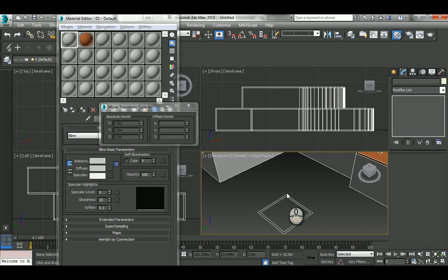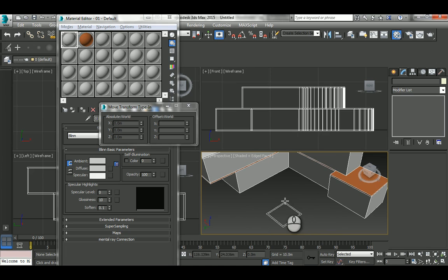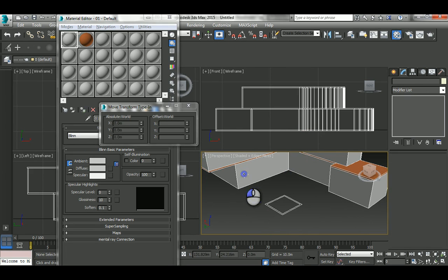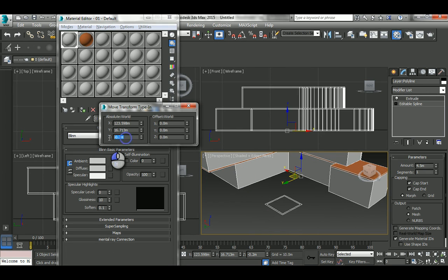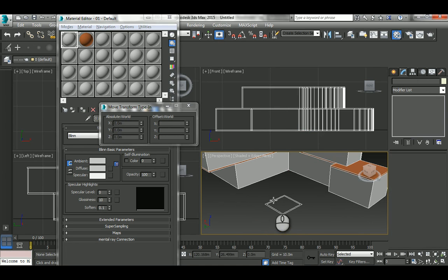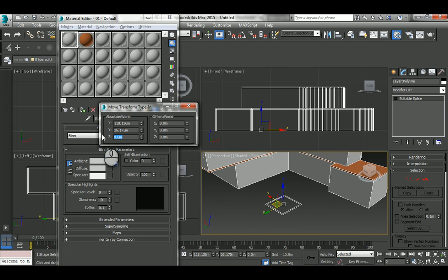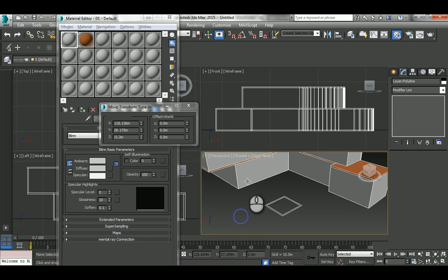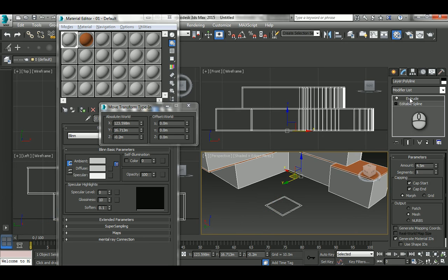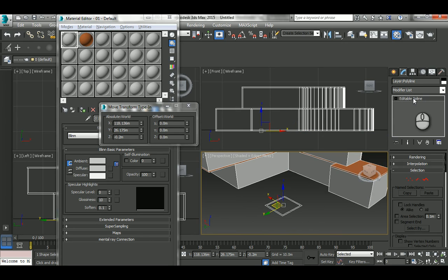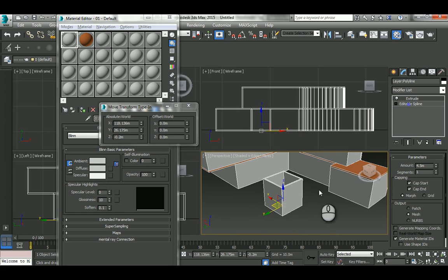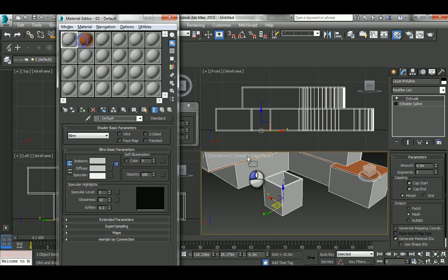and here we go. Notice that this object, this room actually, has the same detail as that. So just click here, copy the Z value of it, then select this object and paste, select this and paste. The same thing for the exit road: select it, copy it from the modifier stack, then select the spline that you just imported and paste. So you don't need to bother yourself with too much detail here. Paste this material here,